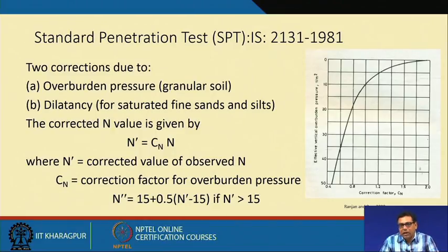So, in one way, if the soil is clay, then we do not need to apply any corrections, but remember that this SPT is mainly suitable for sandy granular soil, but we can use it for the clay soil also. People also sometimes use it for the clay soil, but SPT is suitable for the sandy soil or the granular type of soil.